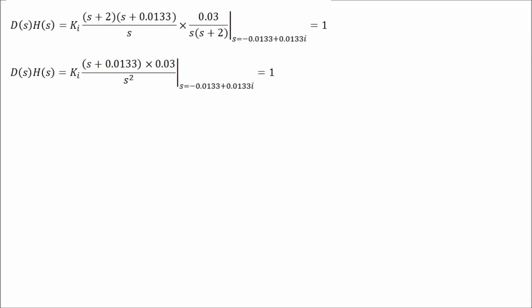And now we can calculate the values of Kp, Ti, and Td and put them in the program. So we need to multiply our compensator with our plant and evaluate it at minus sigma plus Wd. This evaluation gives us a value of Ka equal to 88.9.